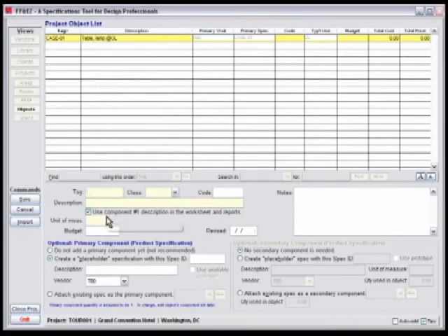and I'll use a tag of light 01. It'll be furnishings, although conceivably lighting could be equipment also. The description would be lamp, comma, table. Now I'm using a general to specific order here because if you use a very generic tag scheme like light or case, putting the most definitive term first helps you sort the descriptions by that item.